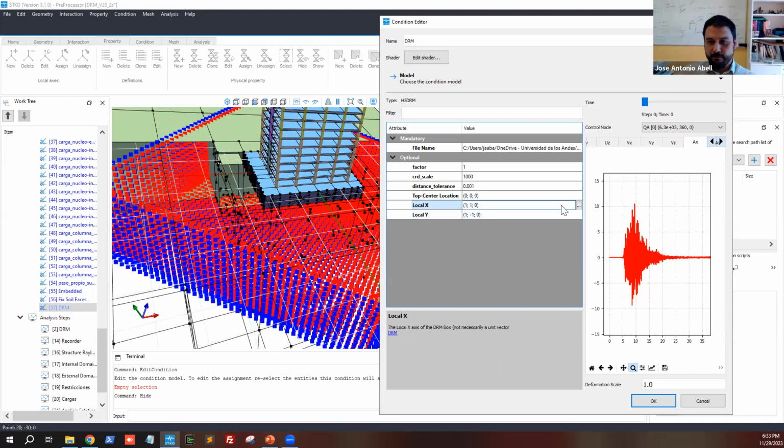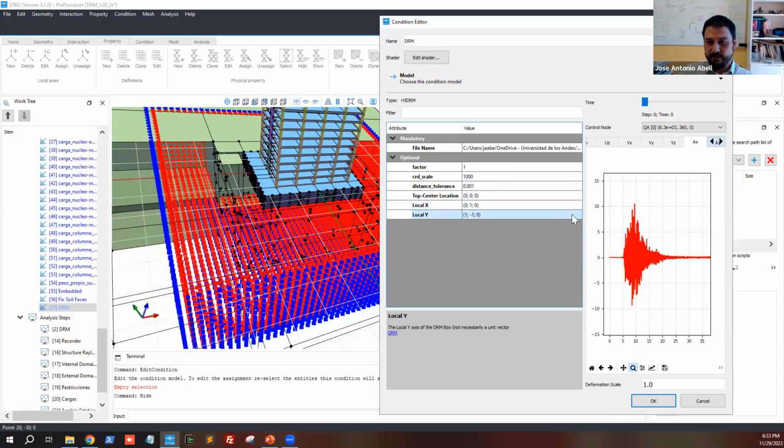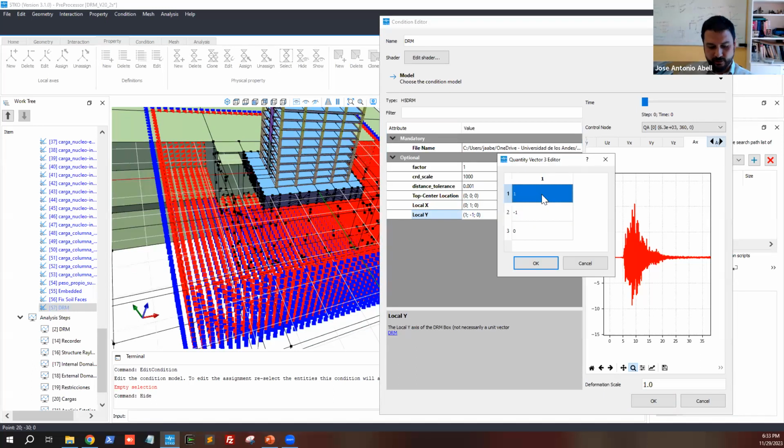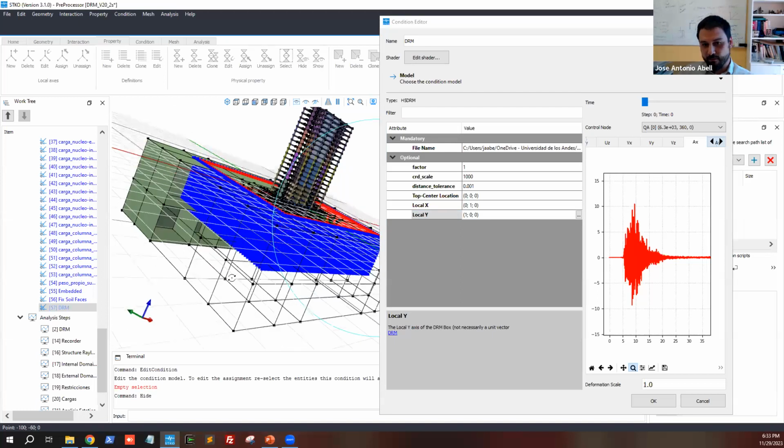And because I didn't mention this, the coordinate system in ShakerMaker is a bit funky. It's with the z coordinate down. So this is why we need to use a coordinate transformation over here that considers the fact that the data comes with the z coordinate positive when we're below ground.